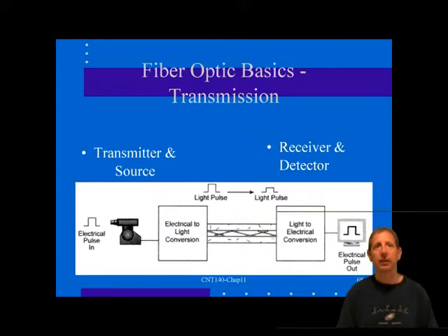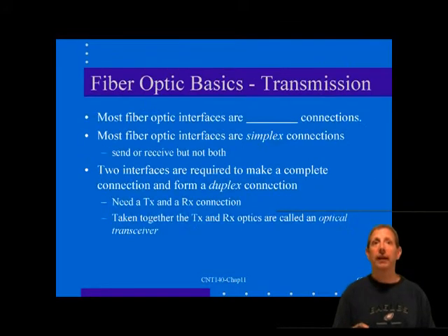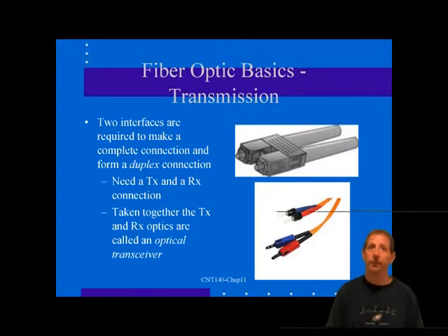At the interconnection location of a multi-strand tight buffer cable, you must be careful to provide proper strain relief for the main cord and the individually connectorized fibers. In many cases, the jacketed cable is very stiff, while the bare fibers are extremely flexible, yet quite fragile.